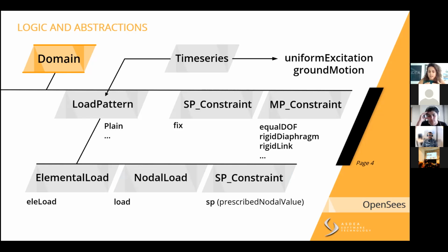We're going to talk about what they are, but in this case, inside of the load pattern, they are prescribed displacements or rotations, prescribed nodal values. Instead, outside of the load pattern, there are some single point constraints commands, but not an SP command. So the SP command is inside the load pattern, while single point constraints commands, like fix, are outside of it. Time series are used inside of the load pattern.